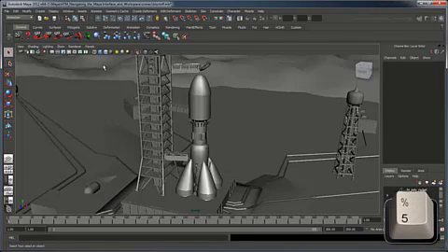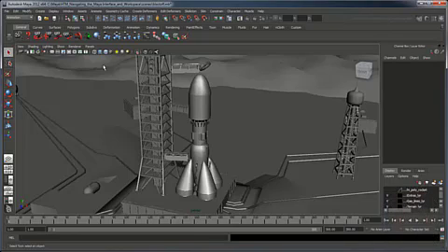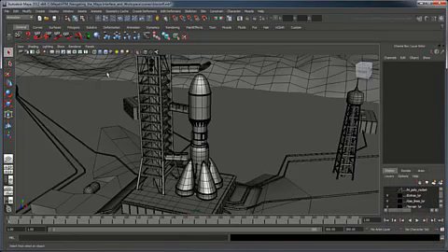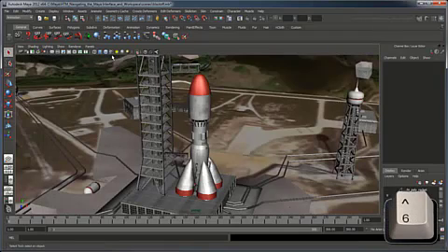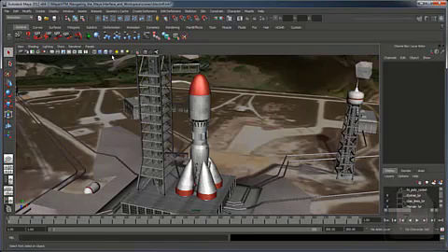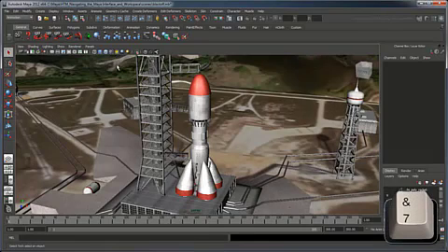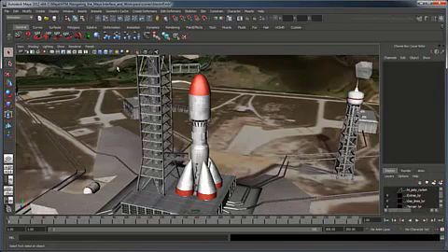Smooth Shade All shows you the base materials, essentially their color. Maya also offers a wireframe unshaded mode that combines these two modes together. Textured shows you the 2D textures associated with each material. And Use All Lights shows the effects of any lights. If you have problems with lighting or textures not showing up in your scene, make sure you are in the right mode.